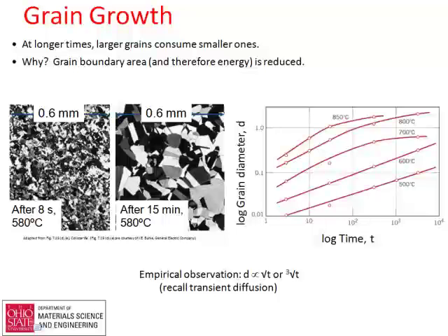And then the last thing you end up seeing is grain growth. If you put even more time and temperature in, those crystals grow to larger and larger sizes. That ends up causing the strength to further decrease. It doesn't do much with ductility. Let's not worry about that. It's a bit too advanced.